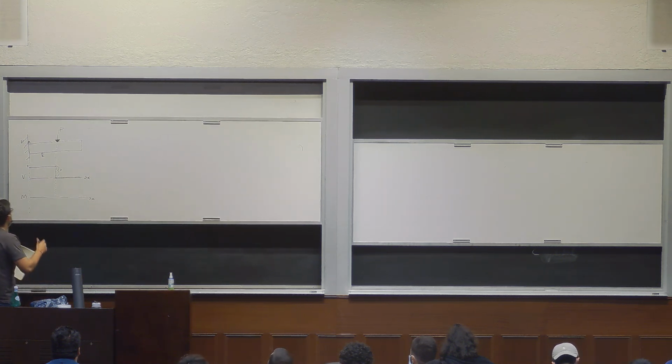It will be acting in this direction because it has to be in equilibrium. If the load is bending this way, the reaction has to be in the opposite direction, and that direction would be negative. So we go to the negative direction here. This is the 0 axis for the shear and the 0 axis for the moment. So you go down to P times L.